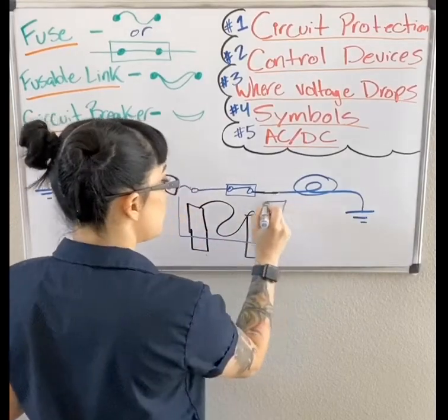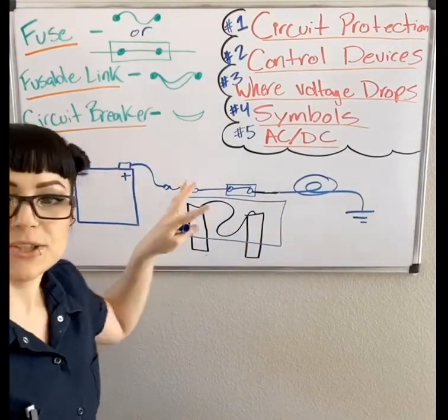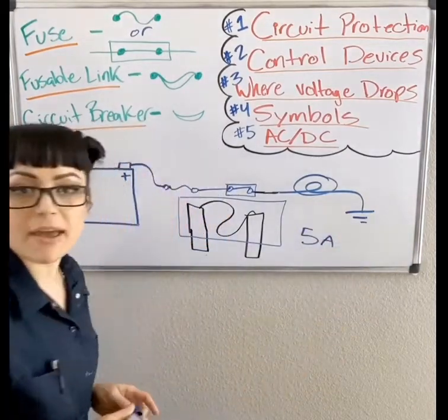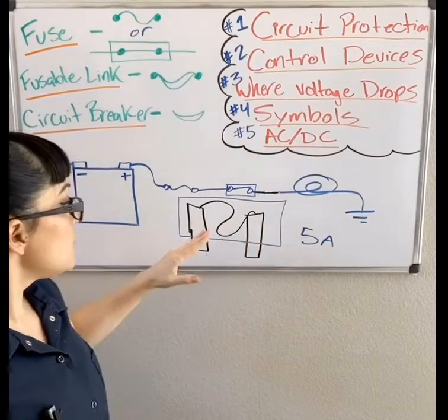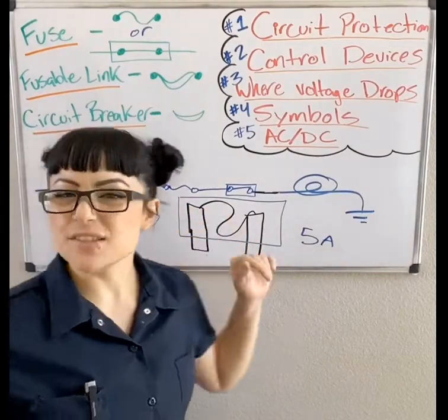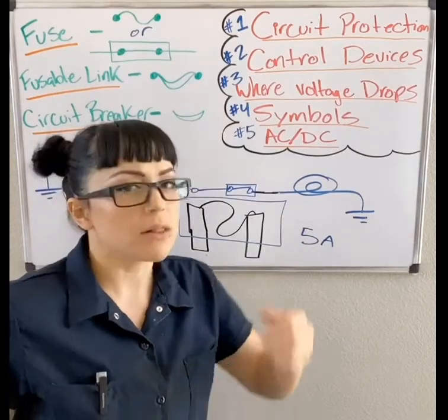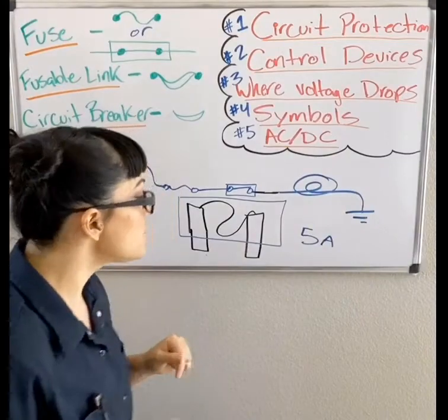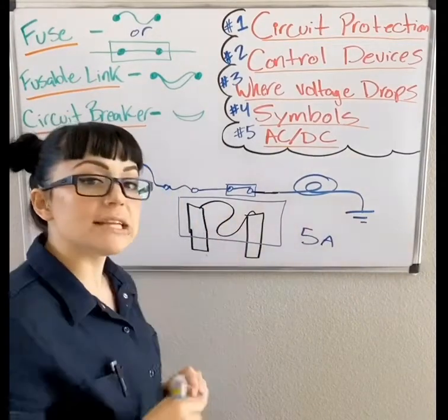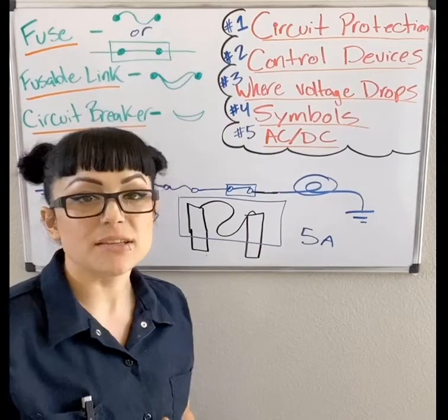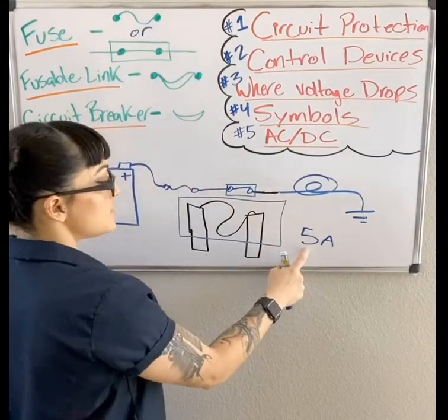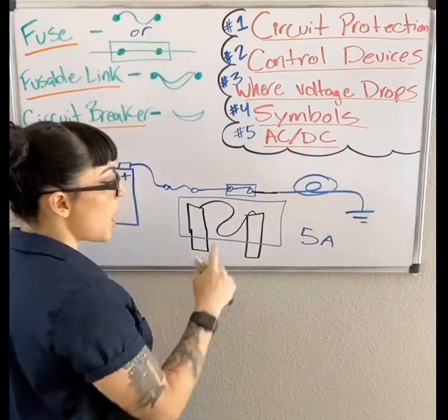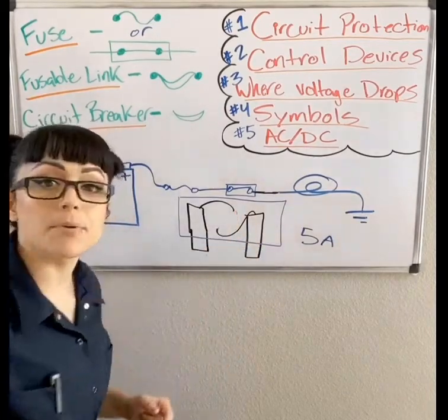because they're usually pretty clear, and I know my picture's getting a little crowded here. Let's say on top the fuse says it's rated at 5 amps. When this reaches past 5 amps, they're not super sensitive where right at 5 amps it'll pop, but once it exceeds 5 amps, this weak link, we call it a sacrificial element because that's exactly what it is. When current flow gets past this, our sacrificial element will get so hot, it'll actually melt and burn up the connection.